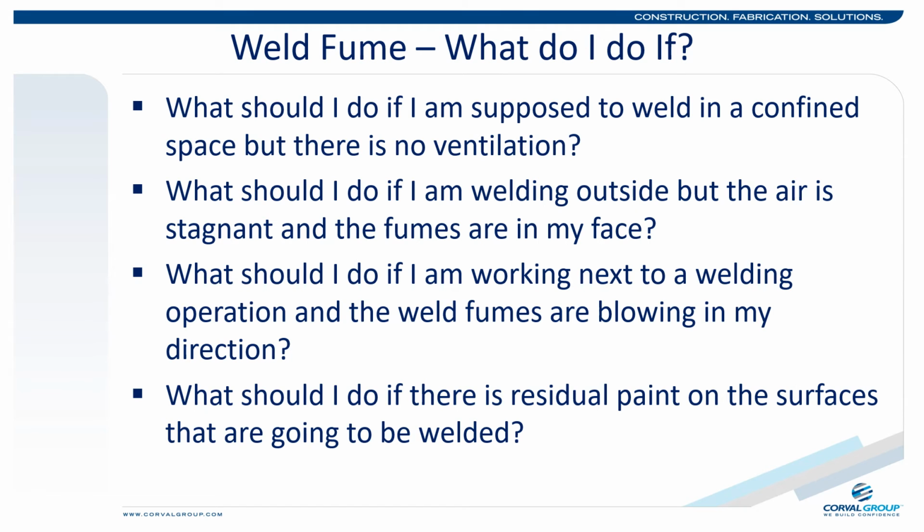Worksite conditions, especially in construction, are usually fluid. That is to say that they're constantly changing. As a component of our task hazard analysis, we can ask ourselves what-if questions. What if I'm supposed to engage in welding activities and have no ventilation? What if the air is not moving from natural ventilation to move weld fumes away from my breathing zone? What if there still is paint on the pieces I'm welding? What do you do when you're faced with situations that you believe do not provide adequate safety measures?